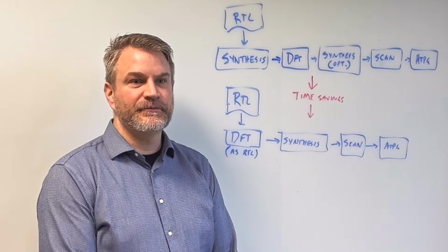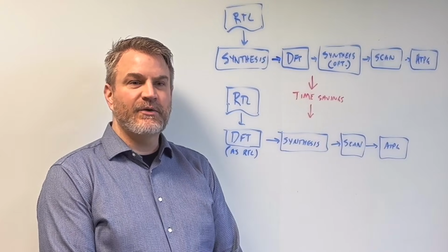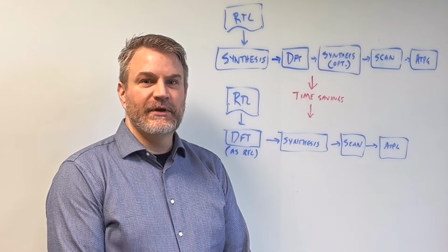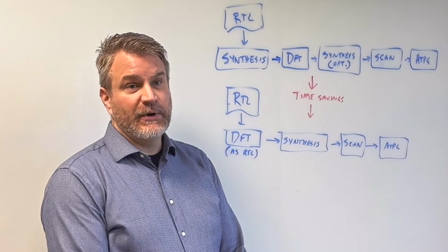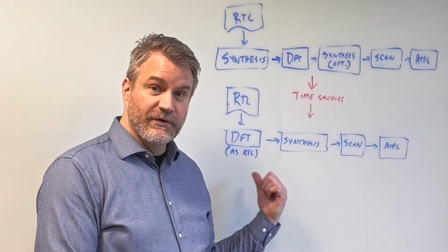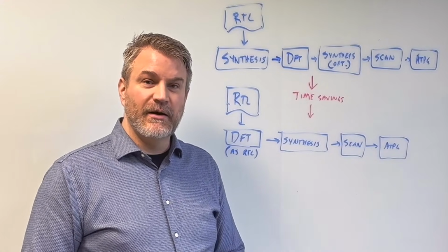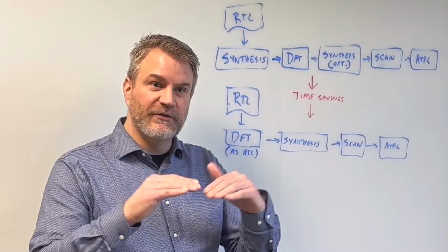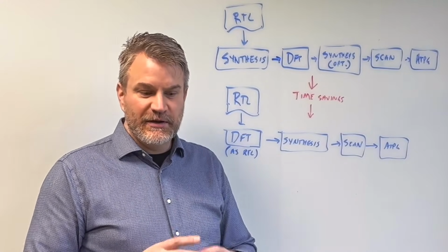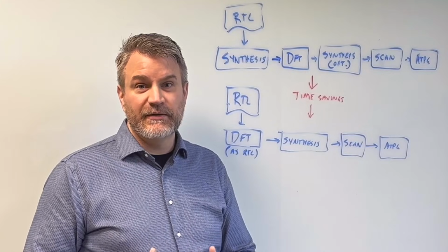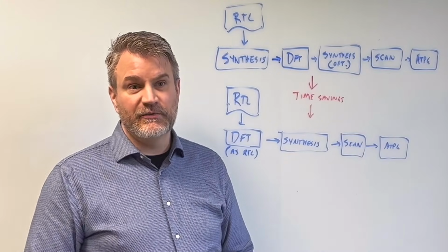Where do you see engineers having the biggest problems or spending the most time when they start getting into DFT? Great question, Ed. One of the biggest problems that we hear about is machine generated RTL. And so that's why our solutions, when you insert test at RTL, come out as human readable RTL that doesn't look like one construct per line, ad nauseam, in the file. It actually looks like readable RTL that you can diff from output to input and see meaningful results.